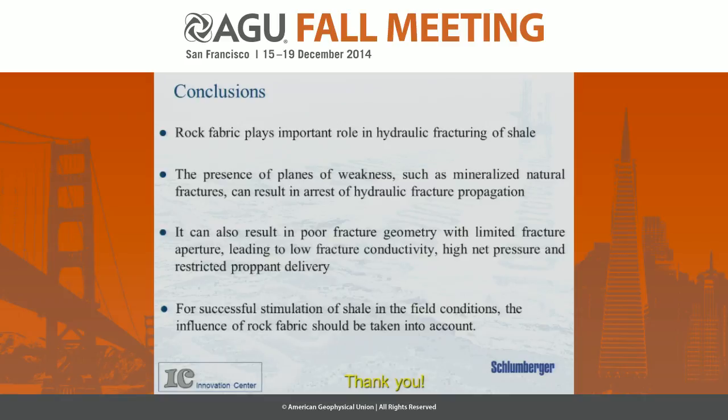perpendicular to the well? Yes, actually, acoustic emission events, as you saw in my animations, sometimes were registered outside of the planes of the created hydraulic fracture, and we call these events related to rock compliance. We definitely have a stressed rock, and therefore very often this stressed rock radiates some events related directly to the stress condition, not only to the fluid presence. But most of the events that were generated by injection were aligned within something like a half-inch accuracy from the plane mapped after the test by the goniometer technique.